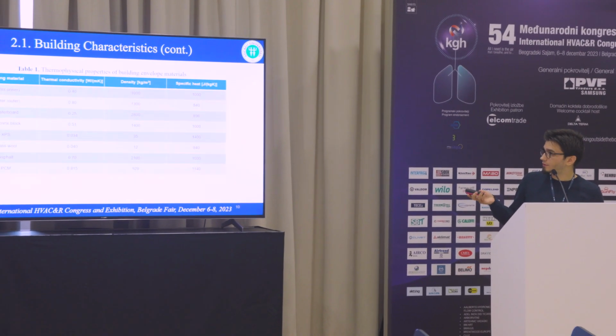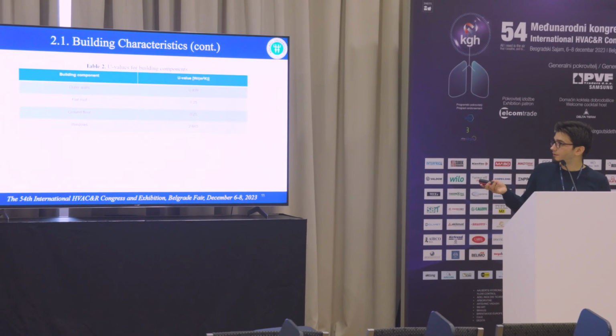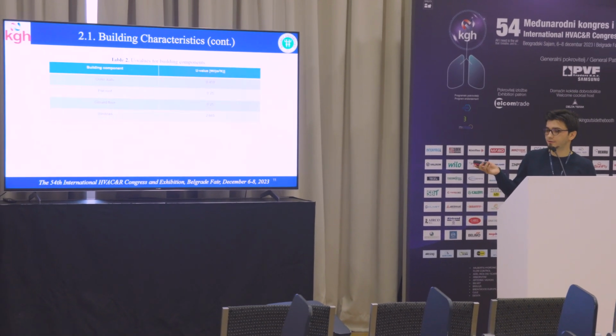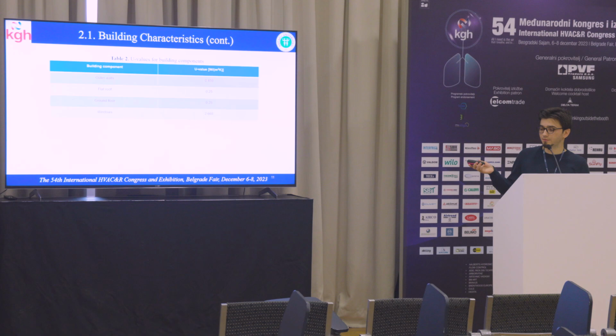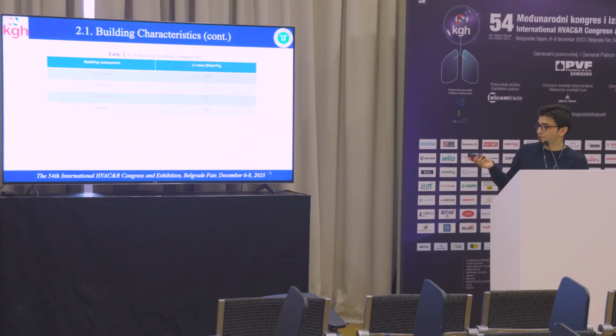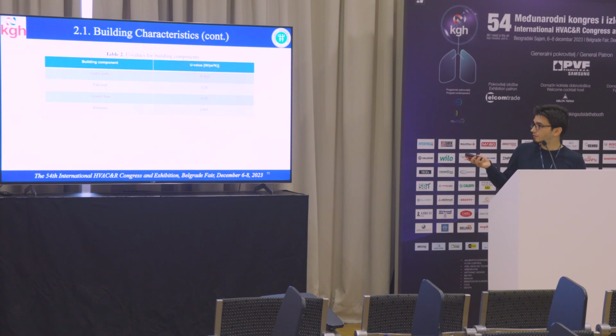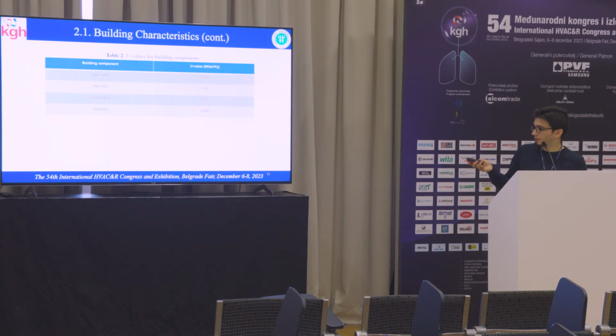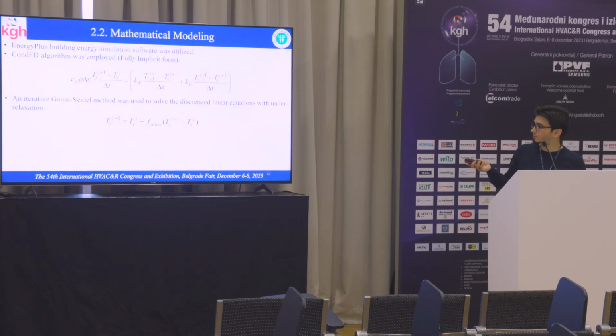And we have thermophysical properties of building envelope materials here, and these are the U values, and these U values are standard maximum limits for buildings in Turkey actually. According to the Turkish standard, outer walls should be at maximum 0.5 in Turkey. A flat roof must be 0.25. Ground and windows, as we can see here, these are the maximum values limited to the U value.